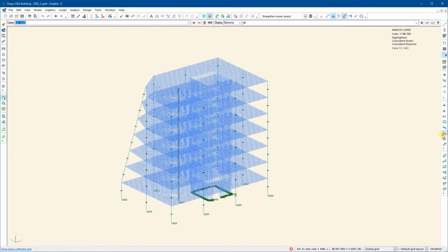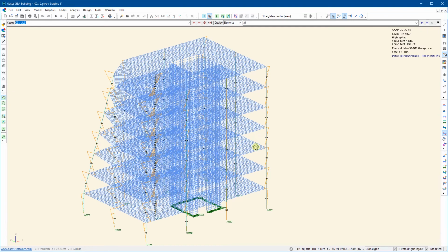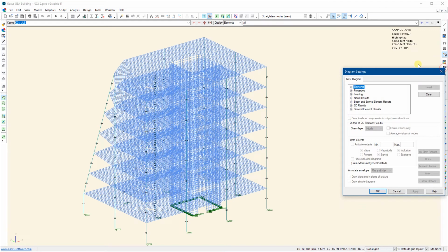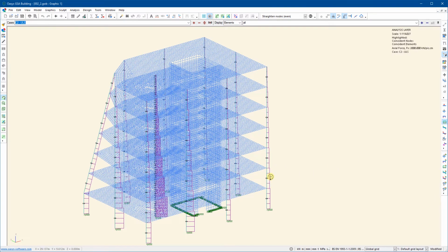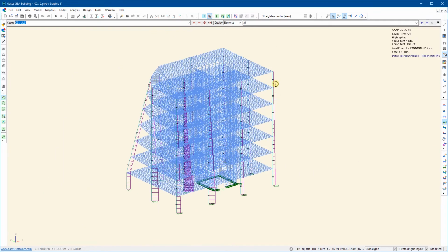if we just, by way of example, we can turn on the bending moments. That's obviously the bending moment in YY. You can come to the diagram options here to look. If we go to beam, spring, force, and moments, we can look at the torsion, the bending in each direction, as well as the axial and shear forces. If we look at the axial force diagram, so these are the diagramming options there, the color contouring options below them. If we look at the axial force, as we'd expect, you get the increased axial force as you come down the columns.